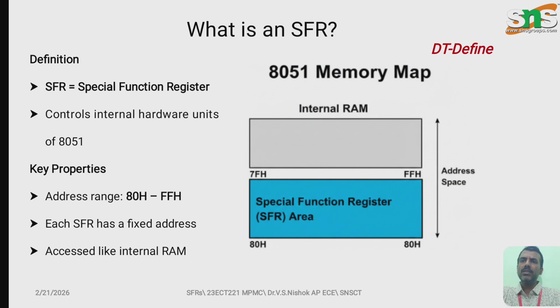So what is a special function register? SFRs control the internal hardware units of the 8051. As we have seen earlier, the timer circuit, input-output ports, interrupts and memory are the main internal hardware units, which are controlled with the help of the special function register.